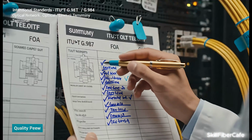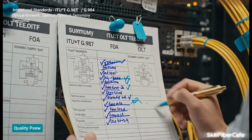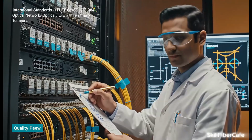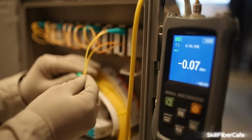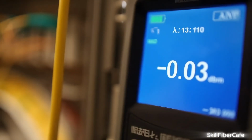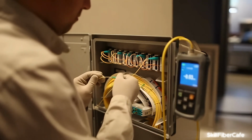International standards ITU-T G.984, G.987, FOA, and TIA-568 give recommended ranges. Following them ensures interoperability and long-term stability. When split ratio or distance exceed the budget, amplification or redesign is required. Future steps involve EDFA and SOA amplifiers to extend reach beyond passive limits.